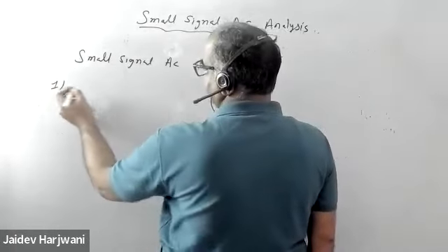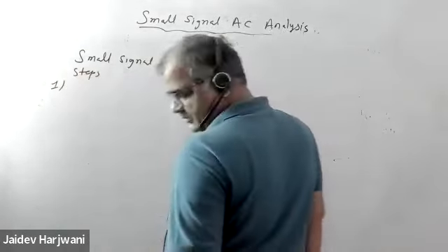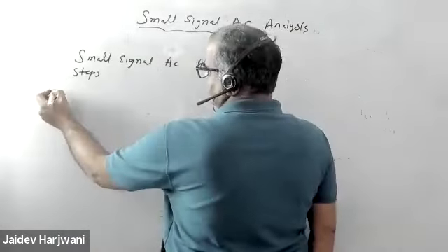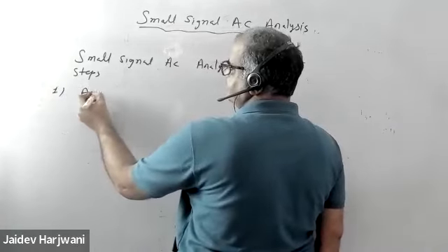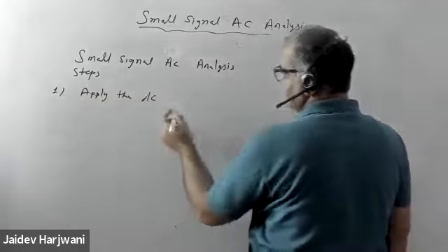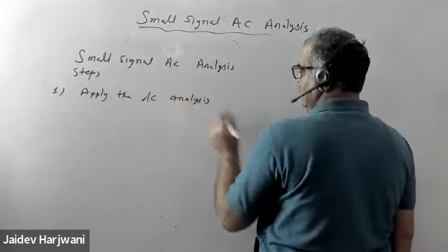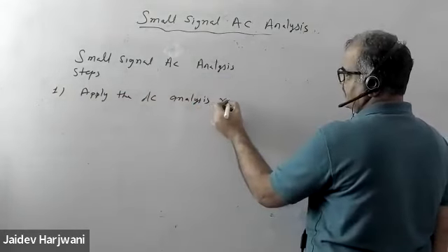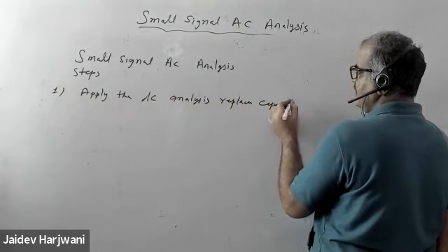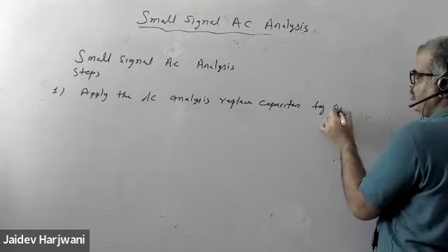Step number one is to apply the DC analysis, or perform the DC analysis. Replace capacitors by open circuits.